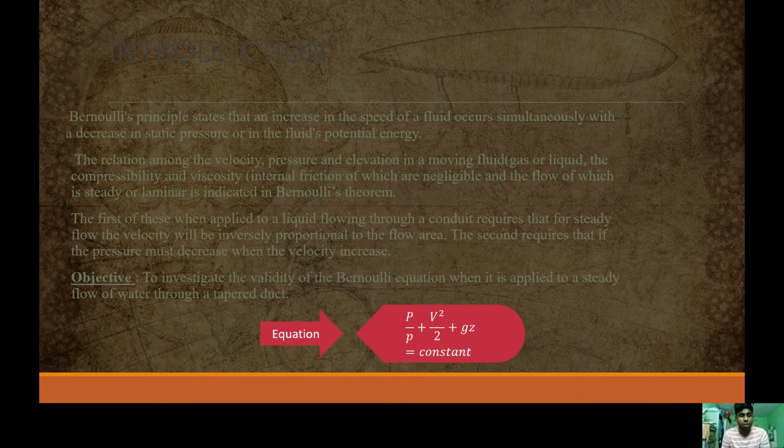Introduction. Bernoulli's principle states that an increase in the speed of a fluid occurs simultaneously with a decrease in static pressure or in the fluid's potential energy. The relation among the velocity, pressure, and elevation in a moving fluid, gas or liquid, the compressibility and viscosity, internal friction of which are negligible, and the flow of which is steady and laminar, is indicated in Bernoulli's theorem.